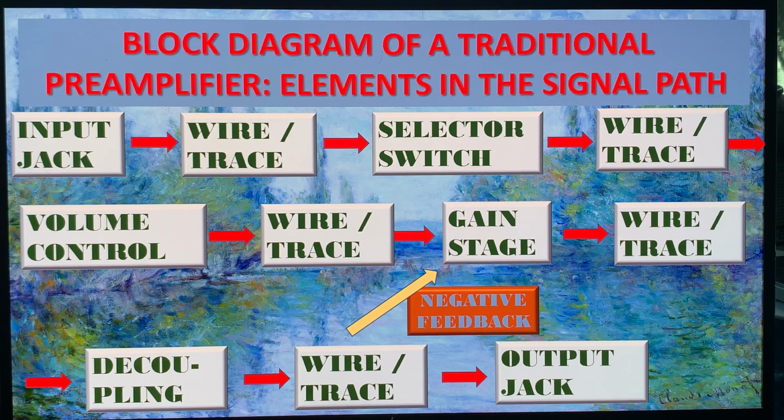I just mentioned it here now so you know what's happening, and the resistor after that decoupling capacitor, that defines the output impedance of your unit. And if you don't know what it is, you can measure the value of that resistor, and then you can tell that's the output impedance of your unit. That was just a curio that I mentioned that's tangential to our subject today.